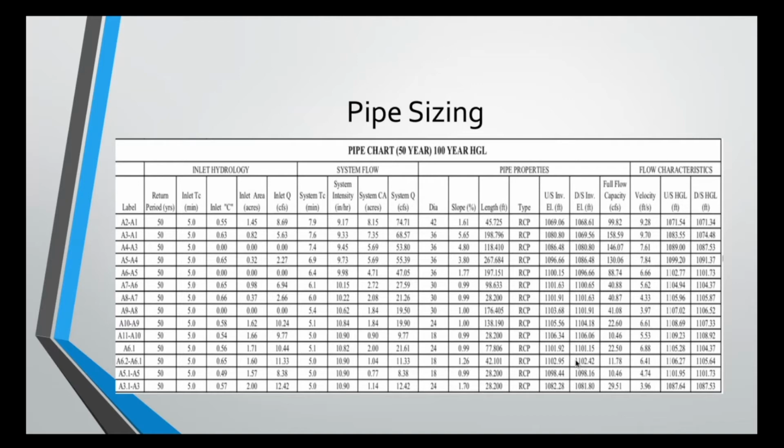In this design, there is a stormwater discharge point that discharges into a creek on the property. A detention pond is not necessary. 4 feet of cover and a minimum of 2 feet separation between stormwater and sanitary sewer is required per Forsyth County regulations.